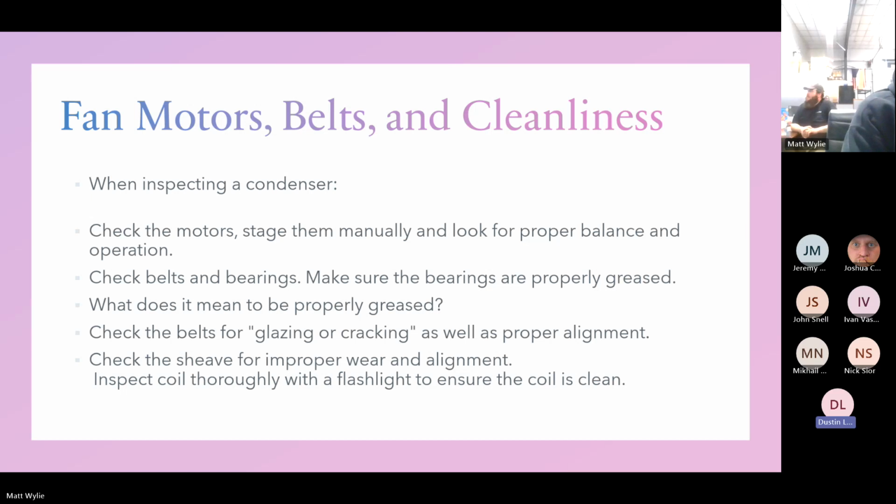Does that help, Jeremy? Yeah, absolutely. Like I said, I had to ask Matt and I asked Nick, and I was wrapping my head around that theory. How does that work? Surely that liquid isn't cool enough, but then it's being metered into the compressor, basically just like a TXV would. So that makes a lot more sense.